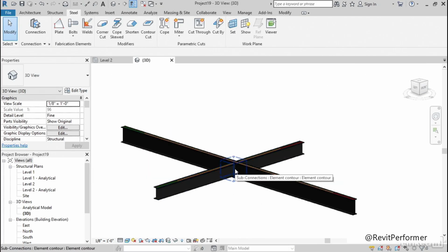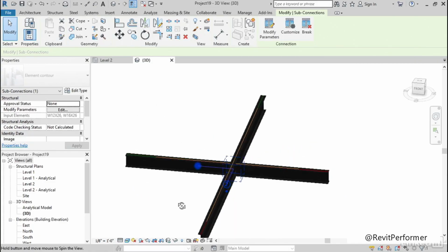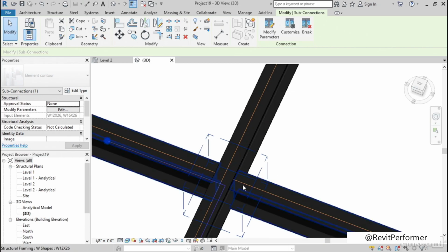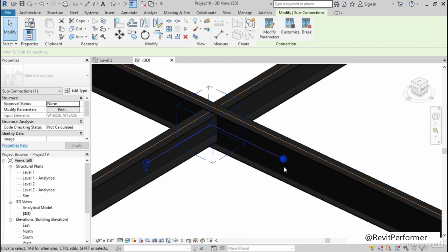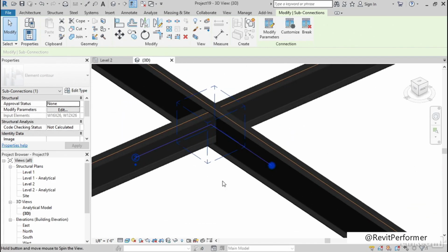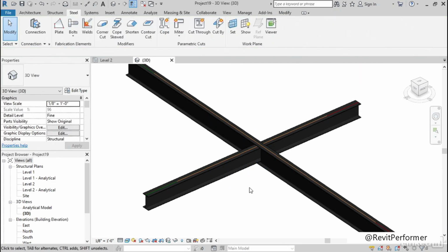If it didn't work on the first shot, what you need to do is select this, and you can just change the direction that it's going in. Whereas this one is going to just basically slice it. It's going to be one beam, but it slices it, you probably never have that. So if I click this again, it's going to punch that hole through it. There you have it. Hit Escape a few times. That's how you bore a hole through a beam with another beam.